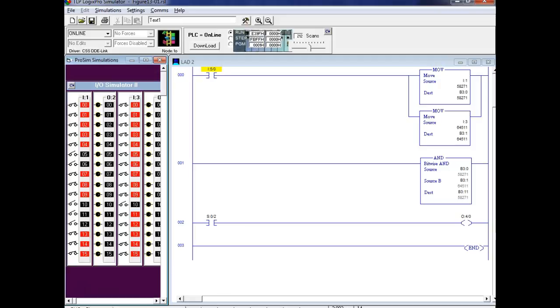Yeah, if I picked up the carry on my next two numbers, you understand? And if my carry was set, I would add 1 to it. If my carry was cleared, I would add 0, and then I would add it to my other number. And now all of a sudden we've got 64-bit math, right?